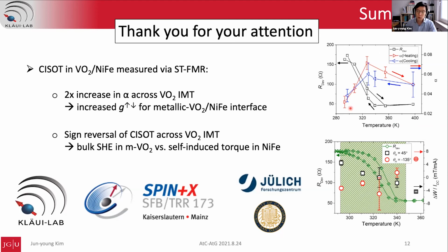Thanks for the question. We performed the measurements at a temperature range between room temperature and up to around 400 Kelvin, and the maximum temperature for spin-orbit torque was around 350 Kelvin, which encompasses the VO2 phase transition as we observed in the device resistance. As for the second part of the question, the ambient temperature will affect it because it is in an open environment. At high temperature, there will be a continuous heat loss to the atmosphere, which we have not fully characterized.